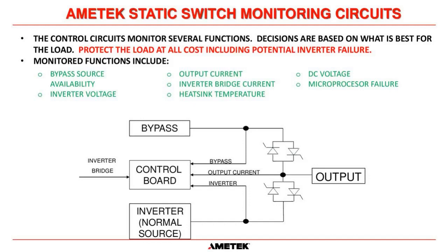The heat sinks where the transistors are located. If we have an air conditioner, hopefully we have it in an air-conditioned room. Maybe it's not. Maybe it's out on a turbine deck where it gets to 130 degrees. I've seen that before. I've worked on an inverter that ran on a turbine deck that was in the open air. And in the summer, it was running at 130 degrees Fahrenheit. The machine was only rated for 105, or 40 degrees C. And this machine sat out there and ran and ran and ran.